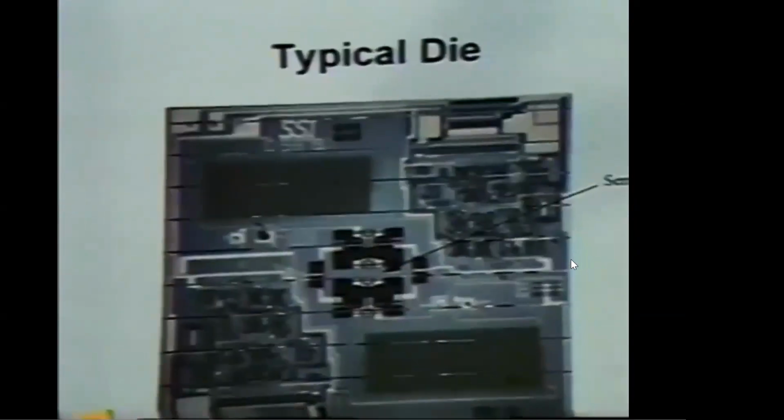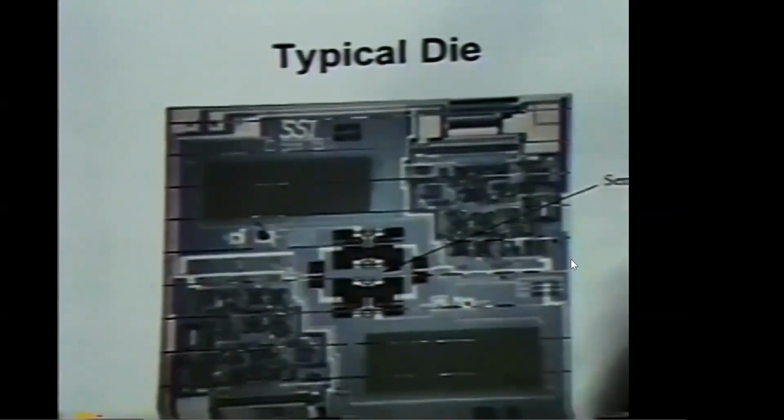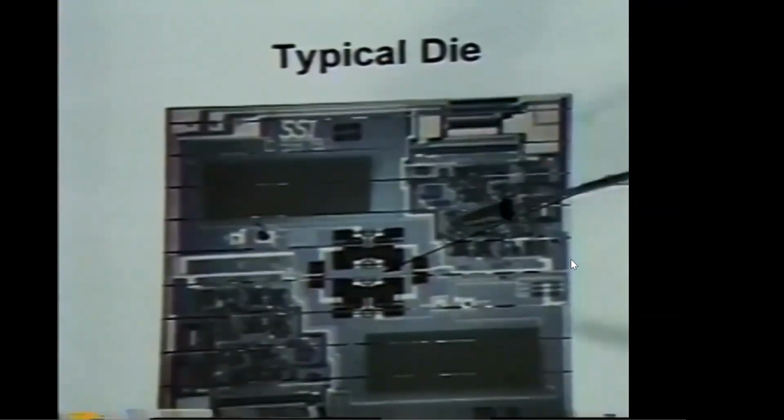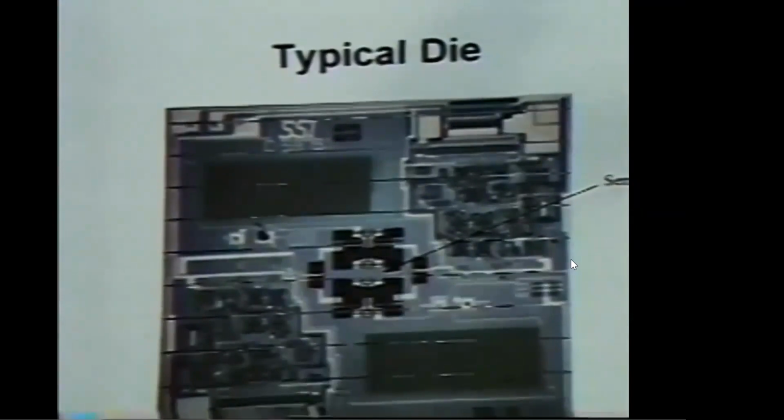So as I was saying, in the center of the die, you can find the 4 cavities that were created the way that I explained earlier. And beside those cavities, you find 2 banks of thin film resistors that we can use to trim those die, trim the membranes to balance them. You also find an op amp, which in this case is the buffer amplifier, as well as some very large resistors that we use for trimming the offset. These are, by and large, bigger than they need to be, so that we can easily reduce the size of this die. In fact, that is currently in process for the next generation pressure sensor.